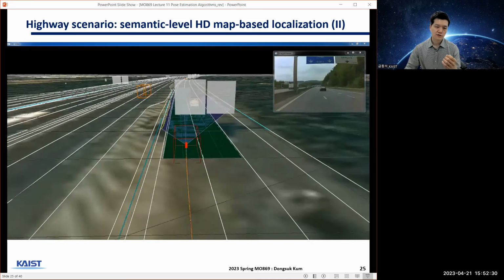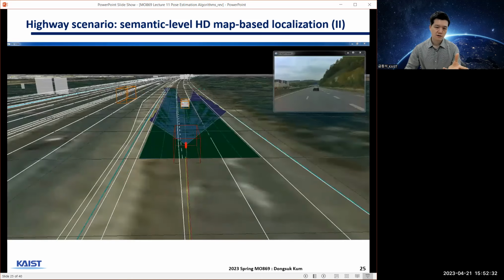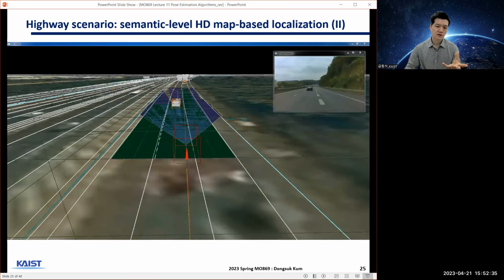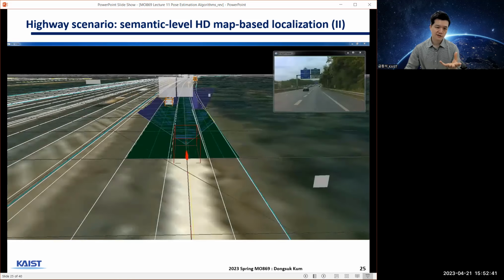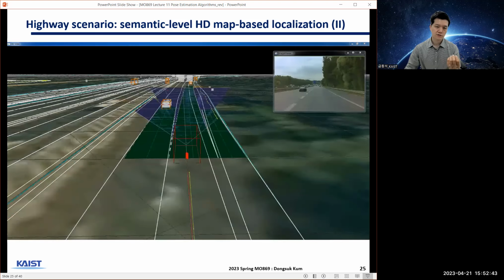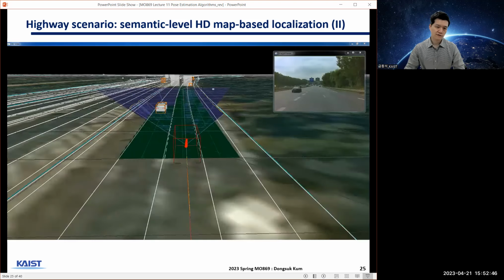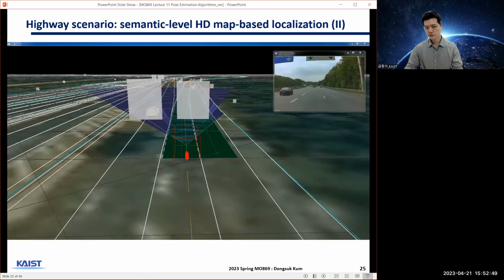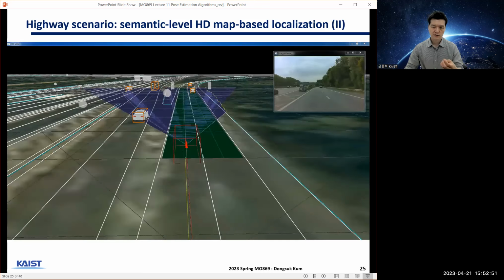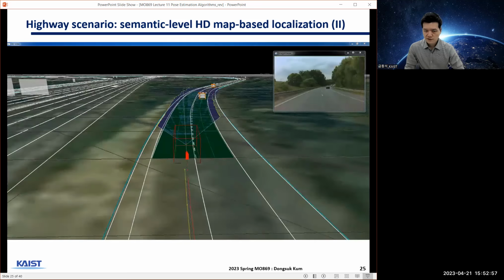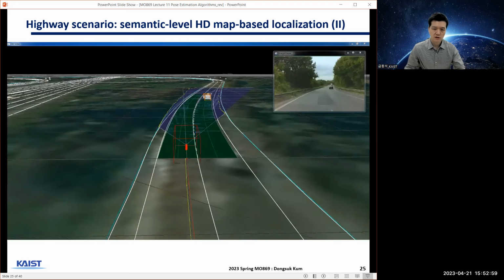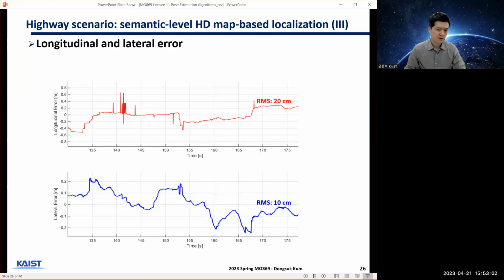But in terms of longitudinal direction, in highway scenarios, things are repeating, unless you have these landmarks, okay? So traffic signs, traffic lights, you can use that information to correct longitudinal position or distribution. But you don't have that information all the time or frequently. So you can correct that whenever those show up, okay?